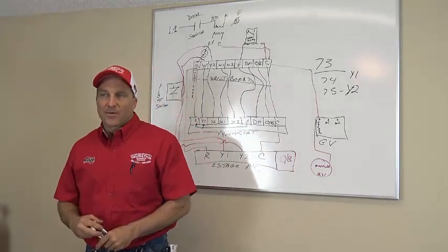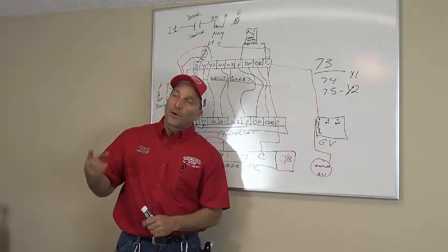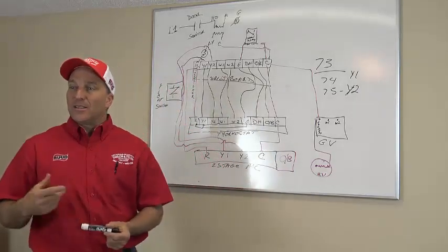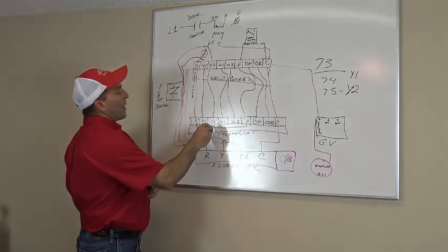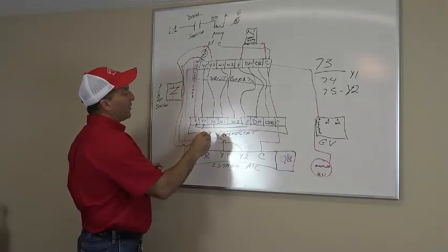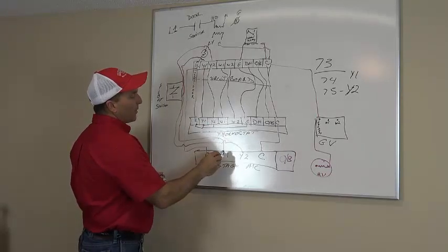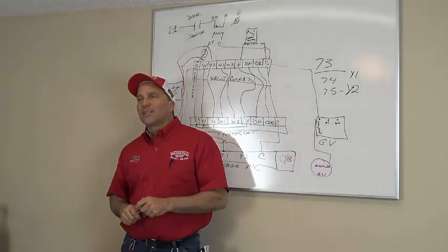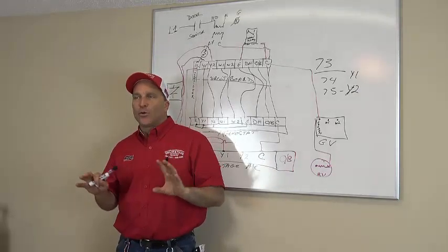Okay? That happened the other day to me when I was checking the system out. I had to go turn the other thermostat on so that both thermostats are kicking in for the second stage to kick in. Now, once it did, it sent voltage to my Y2. Now, what happens when this turns over here to Y2? What happens everywhere else, guys? Tell me what happens. Y2 gets energized, right? Y1 and Y2 are both energized, right? So what happens to my outdoor unit when Y2 gets energized on a two-stage scroll compressor? Tell me what happens in the outdoor unit.